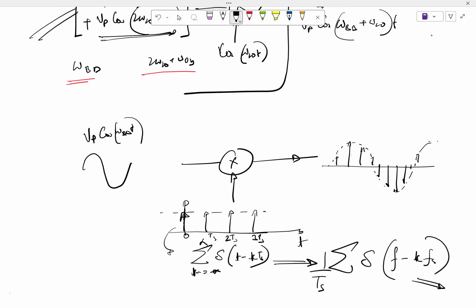Now, time varying systems have been in vogue for decades. And normally, by we I mean the circuit design community, we have been using this in a pretty ad hoc manner, in the sense that we understand how an impulse train looks, we understand how convolution works, we'll just multiply and then do everything in the LTI domain. That's how we have been operating for decades.